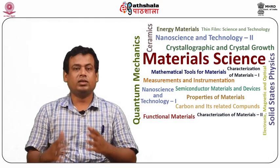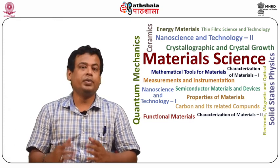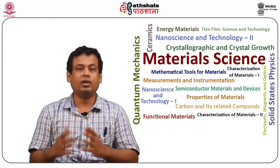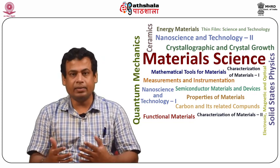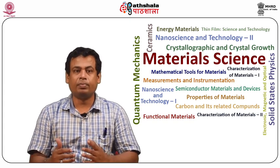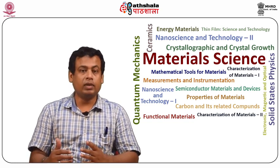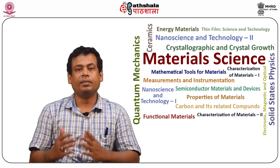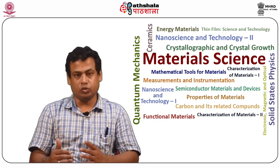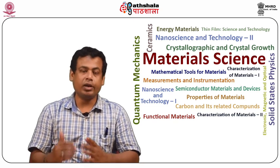So students, let us summarize what we have learned in this module. The advantages of E-beam lithography include smaller spot size less than 100 angstrom, high speed writing with great precision of E-beam deflection and modulation, and good control over the energy and dose delivered to the resist. It provides an ultimate machine for patterning resist with high resolution, high density, high sensitivity and high reliability.